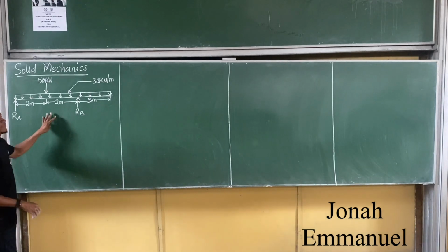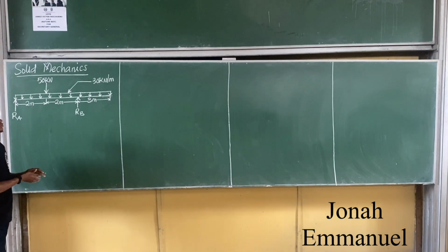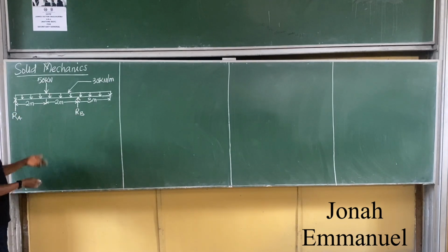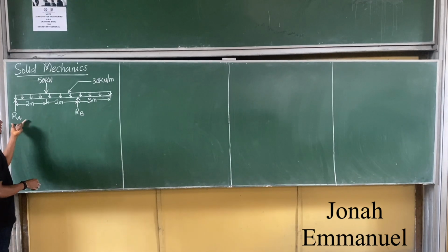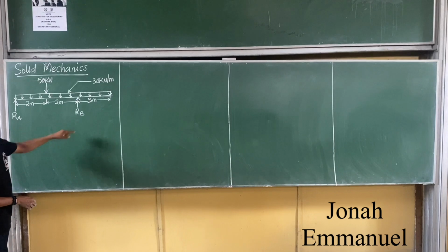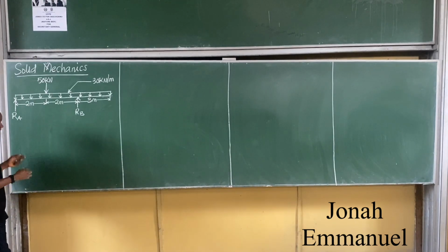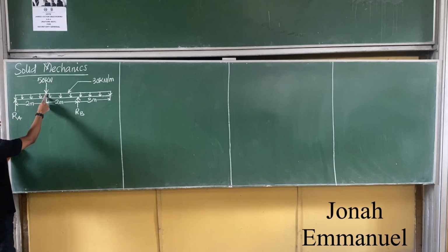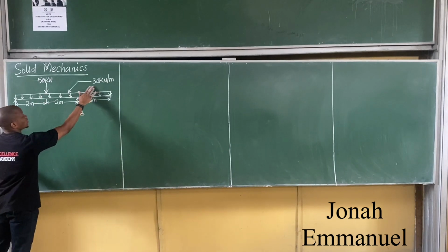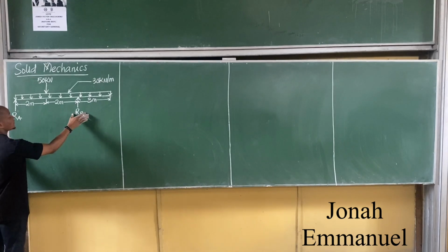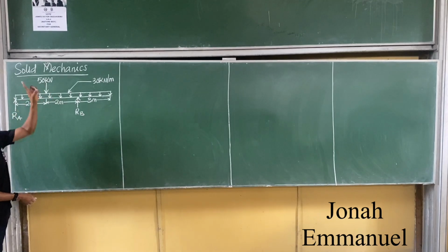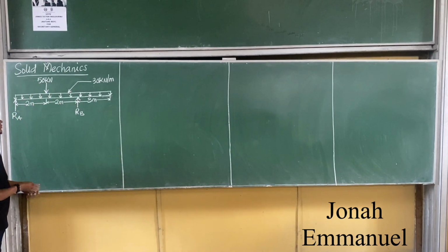Alright, so if you observe this beam here, I've already drawn the free body diagram. There are no support systems, I've already drawn the diagrams. So here's my free body diagram. There's arrow A here, there's arrow B here. If I look at this, there are four forces acting on this system. I have RA, a point load of 50 coming downwards, 30 kilonewtons per meter, which is a UDL, and then RB going upwards. So I have 3 point loads, RA, 50, and RB, and 1 UDL, that's 30 kilonewtons per meter. So how do we solve this?